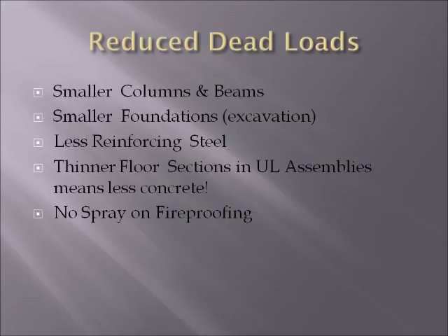When the design engineer specifies structural lightweight concrete on a metal deck, he affords himself many areas of economy. The reduced dead loads will offer savings in steel, in smaller columns and beams and less reinforcing steel. They'll also see savings in excavation due to smaller foundations. The thinner floor sections to achieve a UL or fire rated assembly means less overall concrete on the project, and no spray-on fire retardant will be necessary to meet many of the UL assemblies.